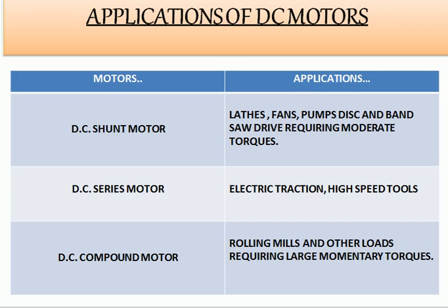In case of applications, shunt motors are generally used where we have to apply the motor for constant speed applications. What do you mean by constant speed? It means we don't need to change the speed of the motor, because in this case the same amount of voltage is given to the field and the same amount of voltage is given to the armature. In that case, we don't have much of a system by which we can control the motor's speed.